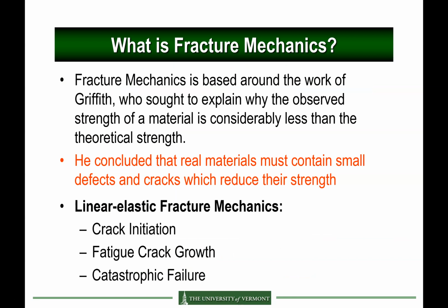So before we go into the detail of the experiment, what is fracture mechanics? Fracture mechanics is based on the work of Griffith, who sought to explain why the observed strength of a material is considerably less than the theoretical strength. His idea was based mostly on the consideration of internal defects and singularities formed by cracks in the solid. So continuum mechanics doesn't apply anymore, and so this will reduce the strength.